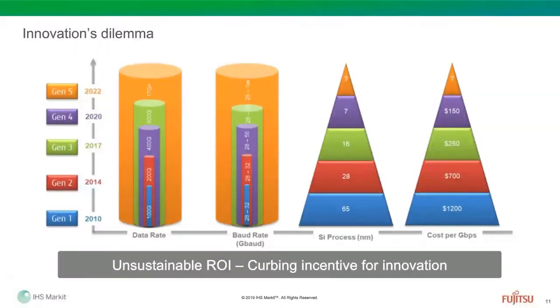Coherent DSP's summary on this slide shows how quickly technology has evolved since 2010. For example, the first generation started with phase modulation, 100 gig per carrier using a 65 nanometer process. Coherent DSP is now in its third generation, with speeds up to 600 gig, packing up to 38.4 terabit in C-band, and offering flexible capabilities in the same system in order to support short to long haul applications. And then there is really no stopping. The race is on to higher speeds and feeds.